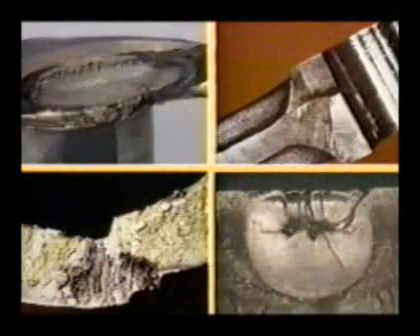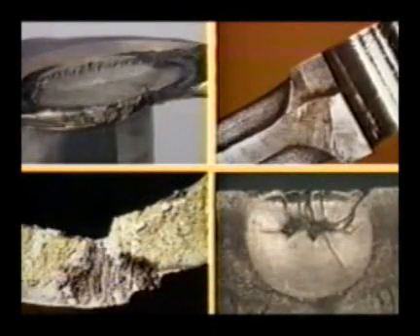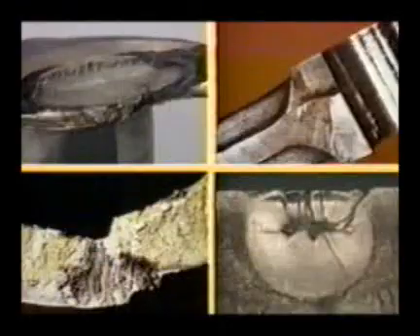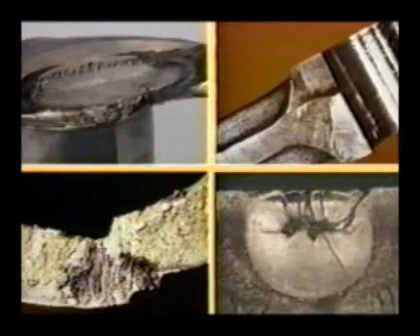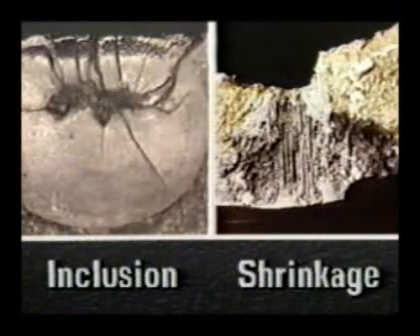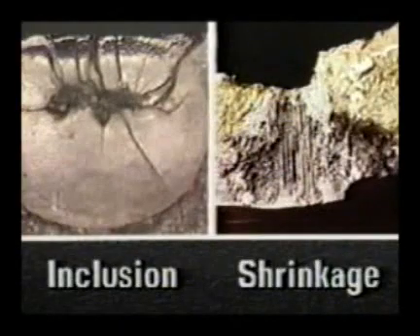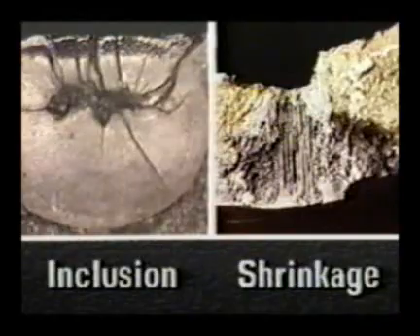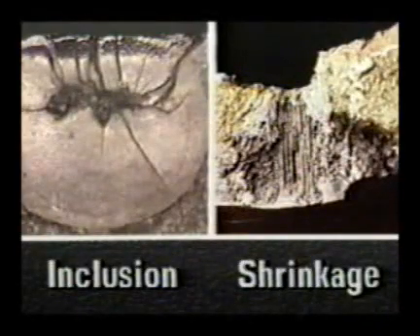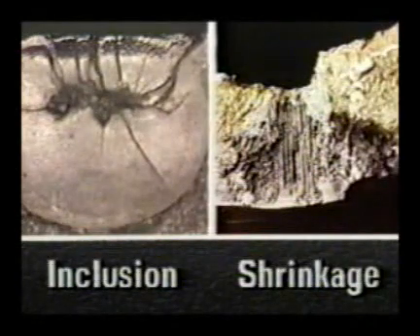Abnormal stress raisers include material problems, process cracks, incorrect geometry, handling damage such as nicks or dents, or cuts and gouges created during maintenance or operation. Material problems such as inclusions and shrinkage voids are usually internal, meaning initiation sites can be subsurface. Inclusion shape may be spherical or long and thin like pencil lead. Shrinkage voids are irregularly shaped cavities. Inclusions can start fatigue cracks inside the part.